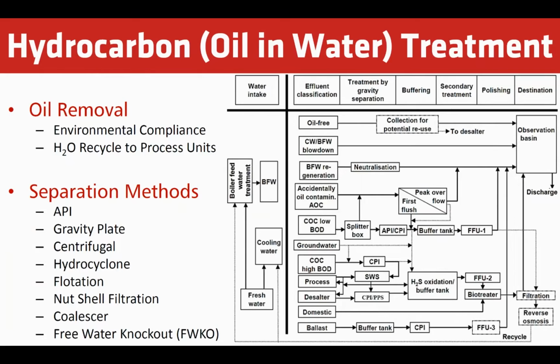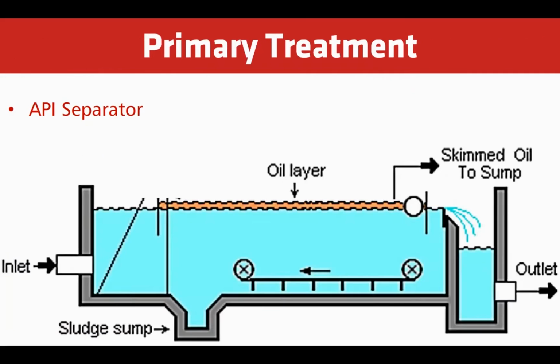to avoid operational issues. Treating oil and water requires several steps due to the complex stream composition, which can include soluble and non-soluble oil, suspended solids, organics, dissolved solids, heavy metals, and various chemicals. Primary treatment removes a rough cut of oil and grease and total suspended solids. API separators use gravity separation and are only meant for high levels of hydrocarbons. API separators are designed according to the American Petroleum Institute standards. The API outlet should have a much lower concentration of oil than at the inlet.